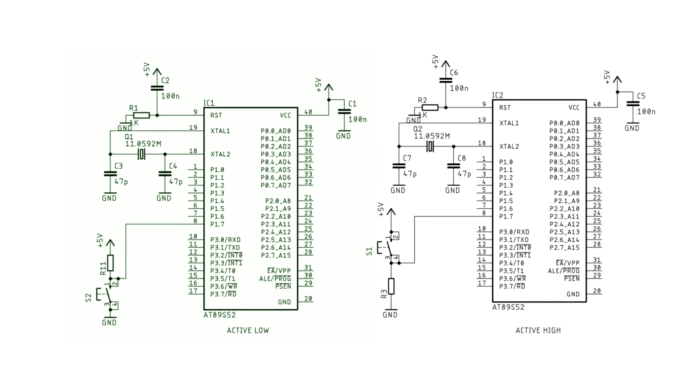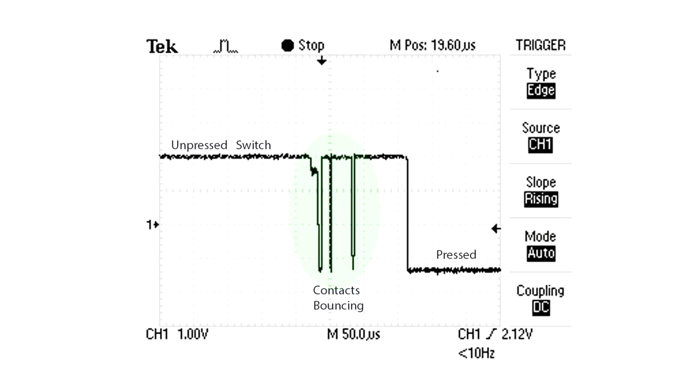We also don't want large current flowing through our MCU when the switch is pressed, but we don't want the resistor so large that the pull-up is so weak that it may not do its job. In addition, because of the mechanical nature of the switch, bouncing occurs that leads to false triggering. It can be solved by hardware or software debouncing. In our case, we will be adding a software debouncer to address this problem.